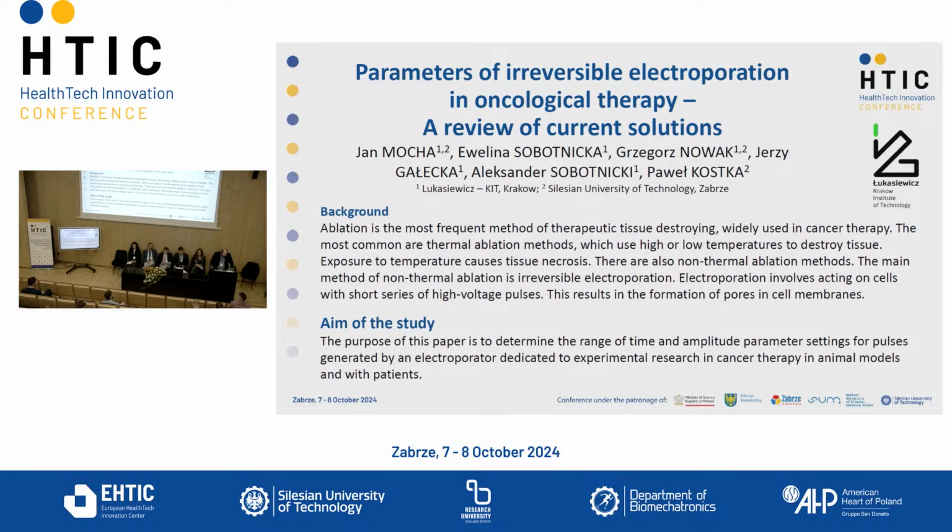irreversible electroporation. Electroporation involves acting on cells with short series of high voltage pulses. These result in the formation of pores in the cell membranes. The aim of the study is to determine the range of time and amplitude parameters for pulses generated by an electroporator dedicated to research in cancer therapy.